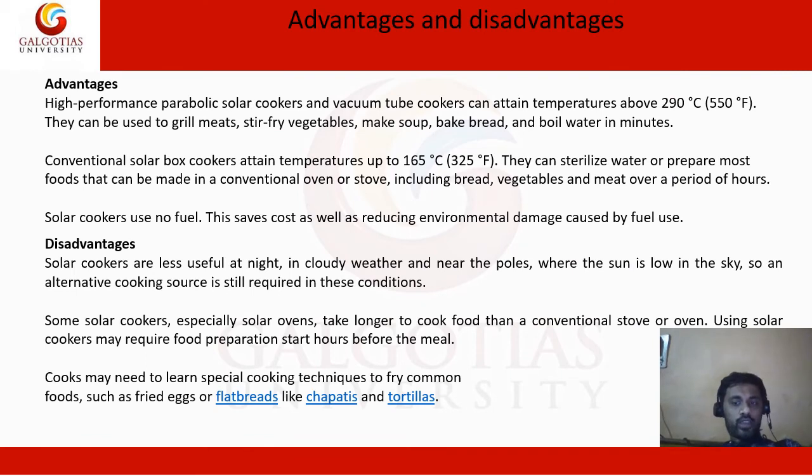So in vacuum tube technology, essentially the evacuated tube solar cookers are a vacuum sealed between two layers of glass. And the vacuum allows the tube to act both as a super greenhouse as well as an insulator. So the central cooking tube is made from borosilicate glass, which is resistant to thermal shock, and it also has a vacuum beneath the surface to insulate the interior. The inside of the tube will be lined with copper, stainless steel, and aluminum nitride to better absorb and conduct heat from the sun's rays.